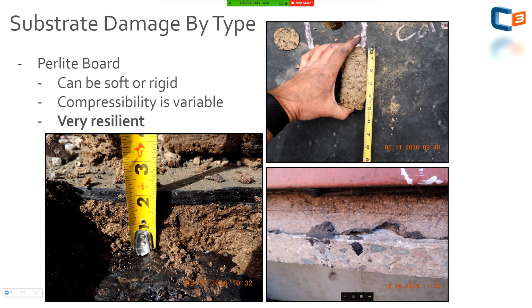You can see on the bottom right, the reason why I show the picture of the deck. This is a double T structural concrete deck. This was actually seen going through the roof hatch. So a lot of times, just as a suggestion, if you can't cut it, look at the roof hatch, because a lot of times you can see unfinished areas where you can see the layering right there. In this case, they applied a flood coat of asphalt. They don't generally mechanically fasten structural concrete like this. Because there are no mechanical fasteners, they're relying on adhesives.